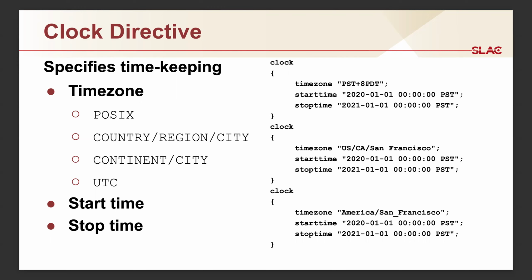When I say infinite, it runs for, I believe, 1,000 years if you start it at the default time and run to the default end. Obviously, that's not very useful, but the simulation essentially will run until it either reaches the stop time that you specify, or it reaches steady state, meaning that there's no further changes pending in the simulation.